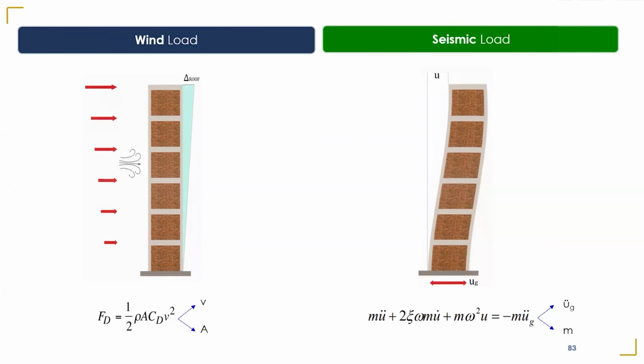So no force is being generated along the wind because it's streamlined. But it's creating a lot of force perpendicular to that, which basically lifts the plane up. So we don't want the building to have that effect. So we don't want a streamlined building.